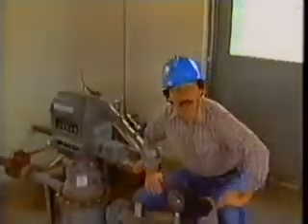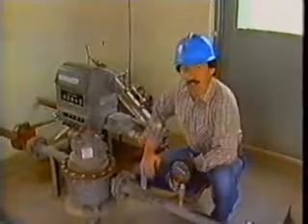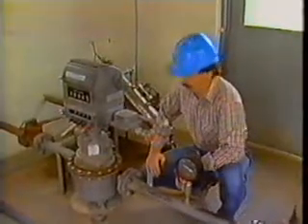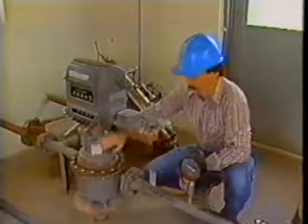So far we've talked about inferential meters. Let's look now at a volumetric measurement device, the positive displacement meter. This meter continuously divides the flowing stream into known volume segments. The segments are isolated momentarily, counted, and then returned to the stream.